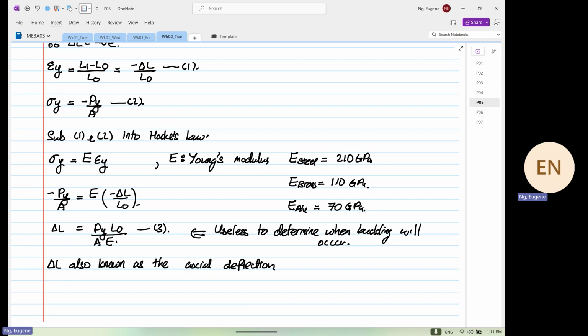You're partly right. What sort of deformation, what sort of loading can give you deformation like this? That's not axial. If I were to turn this around, and if I were to push my left hand and right hand upwards, what deformation pattern do you see? Yes. So can you see, if I push my fingers left and right upwards, what's the sort of deformation I get? You get a smiling face or sad face. If I put my structure this way, and if I press it down, isn't the deformation pattern the same?